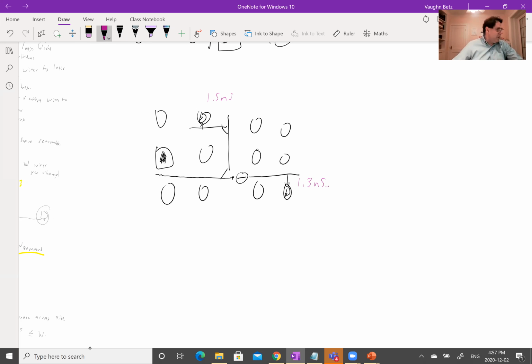But with 100,000 fan outs, you're not going to get the skew to 0, even with a very clever algorithm, because this routing network wasn't built with enough flexibility for you to precisely balance skew. Several people also highlighted, well, you could also waste some wire, and that's true. In order to build skew balanced networks out of this regular wiring, I'm going to lose some efficiency in terms of how much wire I use.